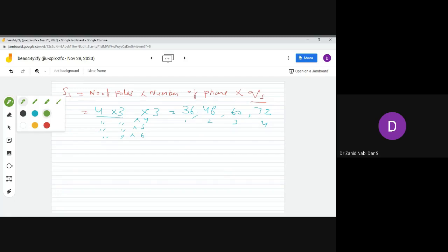Here, I will again write down for your convenience. Slot pitch for open type slots would be around 15 to 25 mm.